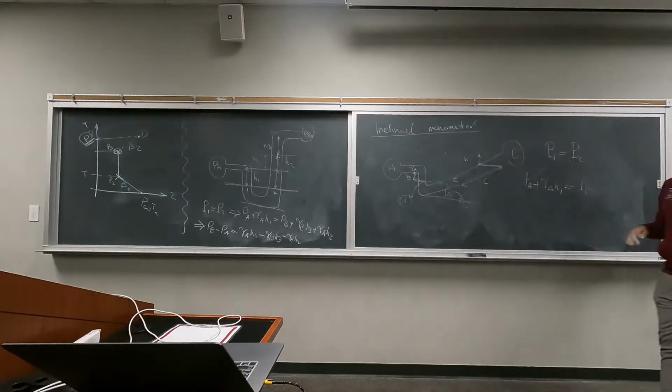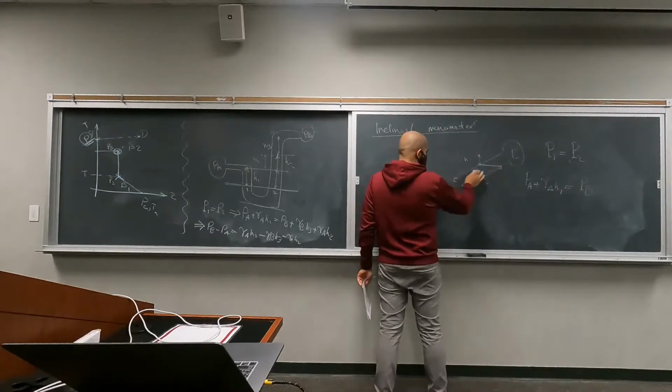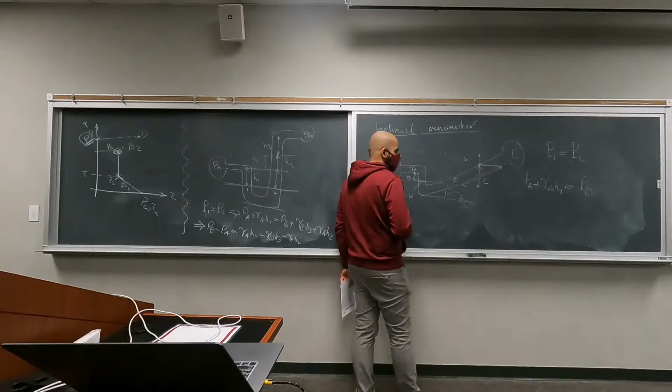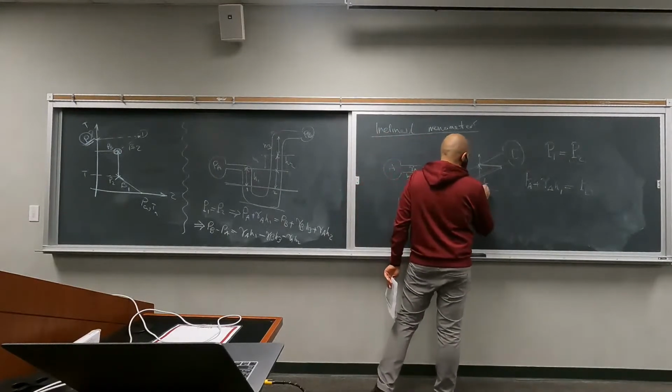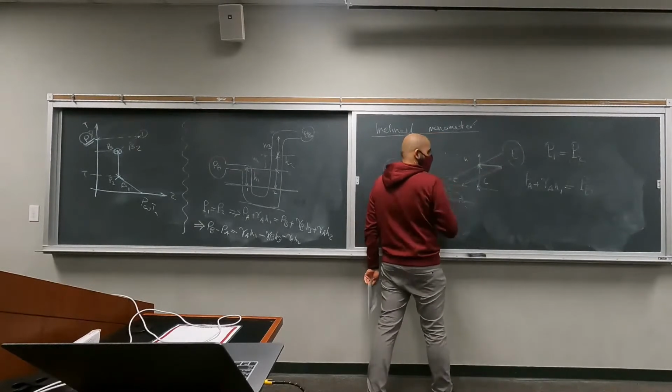Whenever you see this type of problem, you have to think about the definitions we use for pressure, the hydrostatic pressure. Hydrostatic pressure is always a function of your height, or your depth. The height of this liquid column is this, right? It is very important. So the pressure difference is a function of this distance, not this length, right?